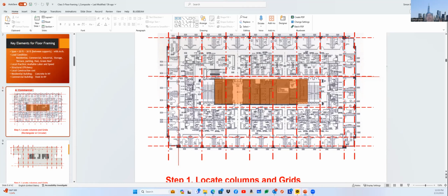But that is more of a tenant-related issue. For structural, overall fire, or evacuation purposes, we must have 2 egress stairs. So pay attention: in your final project, you need to address 2 egress stairs and a number of elevators. That is a very essential item you need to address as well.